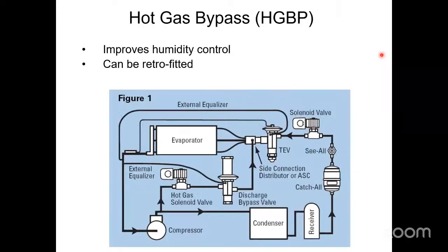Hopefully that makes sense. Other things we could do for capacity control, assuming that you're not going to do chilled water, because chilled water, it's a 1-second discussion. We're done. Chilled water modulates, we're good, right? Let's say you're still on compressors, though. You can use what's called hot gas bypass. There are some rules against this in the modern energy code that limit it, but you can still use it